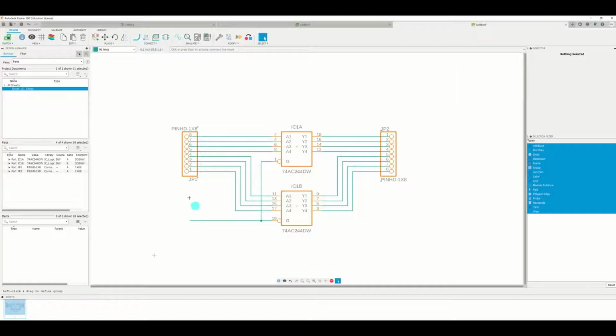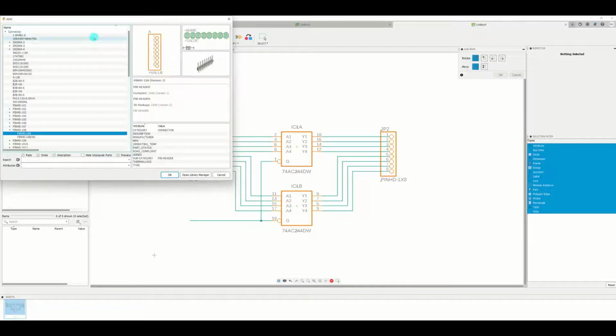So we place a component, let's say a 3 pin, and then we make use of the VCC and ground for the other 2 pins. The VCC and ground are not shown here, but later we can display them so we can have the connection. So again, select the component, and we look for, say, 3 pin, wherein you have one enable and one ground and one VCC. This one.